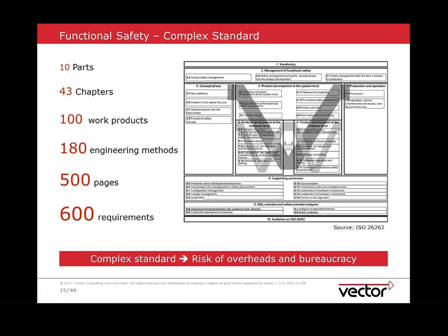We should also be very clear that there is a big difference between requirements suitable for a high-risk environment like an ASIL C or D, or a rather low risk where many of the requirements really boil down to something which you probably already do, that applies for ASIL A.